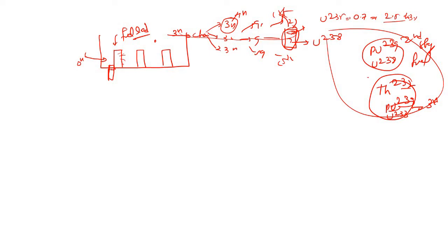So if we insert control rods completely, if control rods completely surround the fuel rod, then these neutrons cannot hit the fuel rod. When they are not hitting the fuel rod, no reaction is taking place. No reaction means no energy, no output. So control rods are inserted completely only when we want to stop the nuclear reactor.